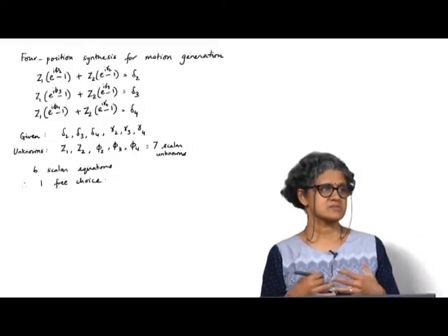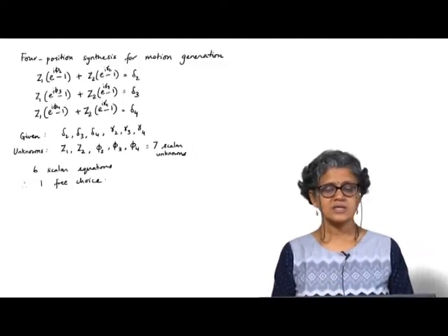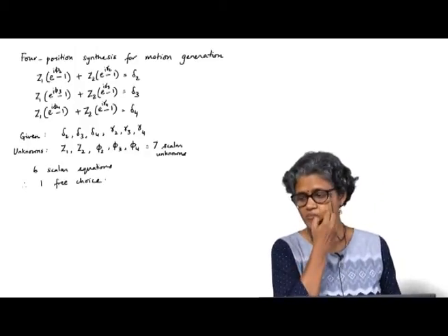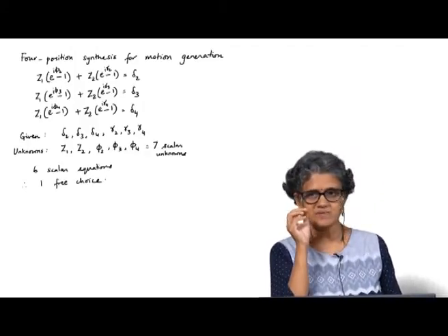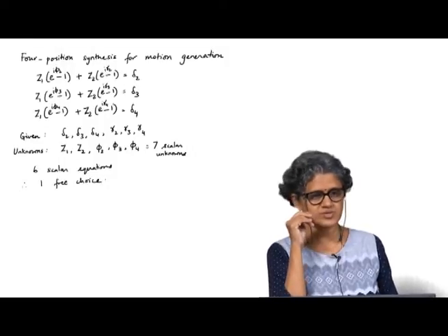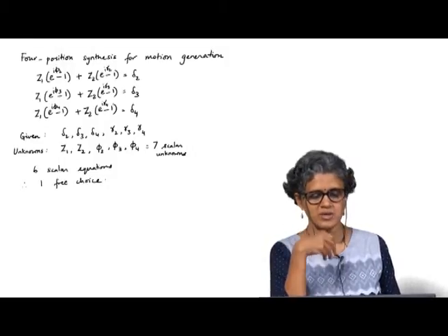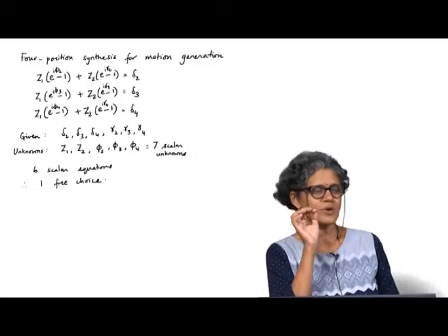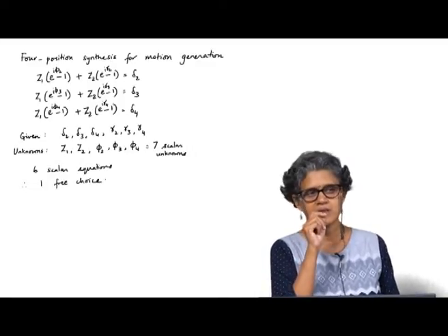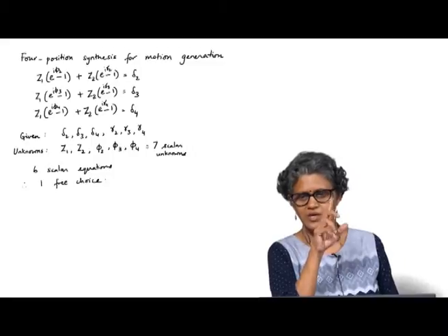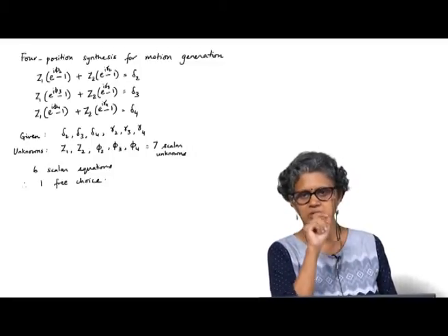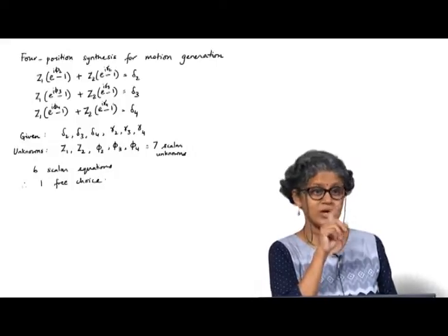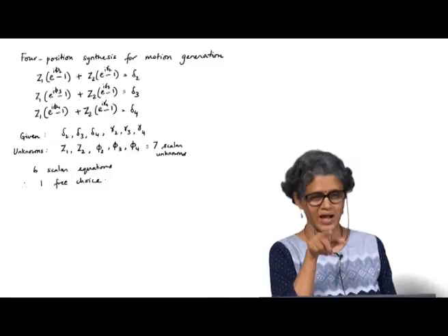which means theoretically you should have an infinity of solutions. But we saw with the graphical method that we ended up with a unique solution for the 3 position problem, and we did not explore the 4 position, although you have some clue. For instance, if you take 2 positions and take the pole, say P12, as one of your moving pivots, its location does not change between position 1 and position 2.